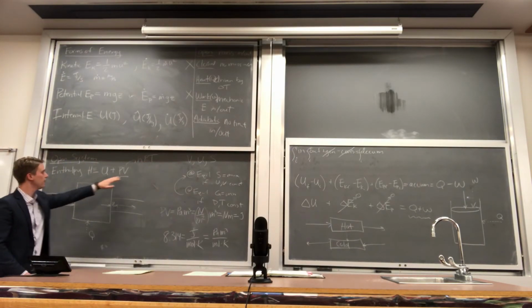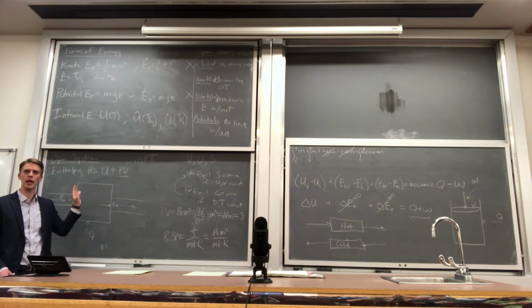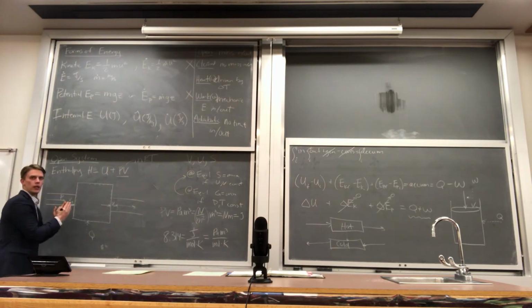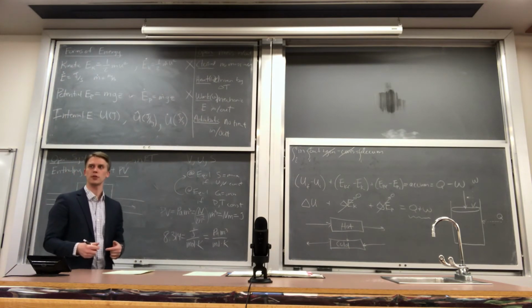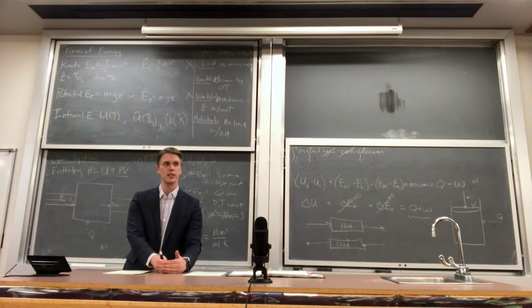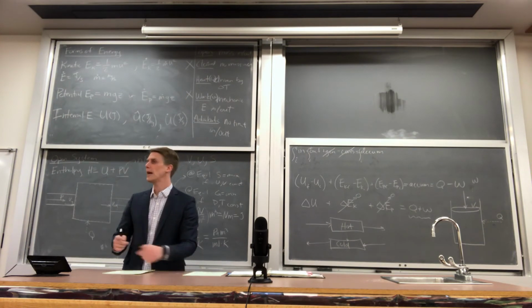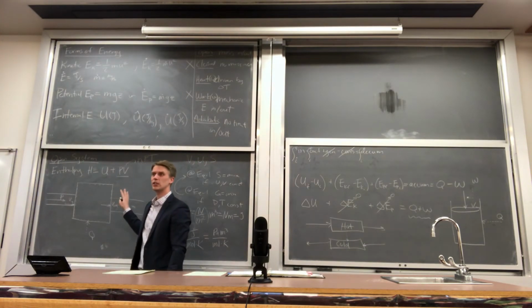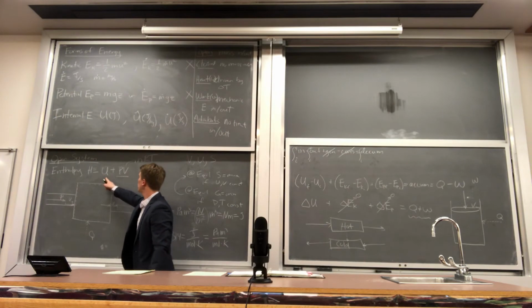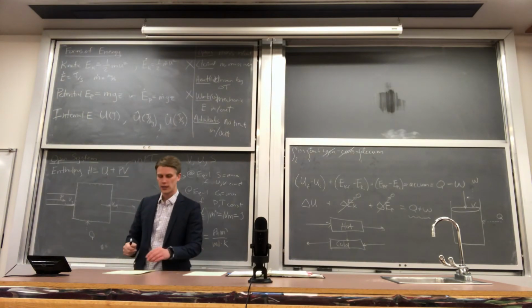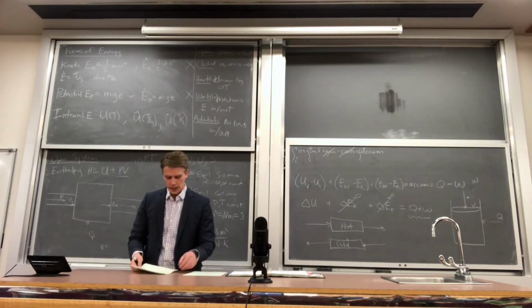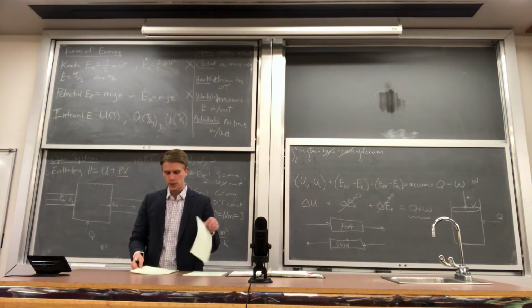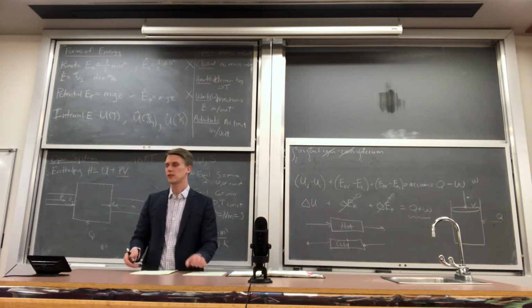For a real fluid, this is not the case, right? So for a real fluid, the enthalpy is different as a function of pressure and temperature. And so if you look at your steam tables, you'll notice that the enthalpy indeed does change when you change the pressure. But for an ideal gas, which is going to be the lion's share of our calculations, the enthalpy and internal energy are only functions of temperature. Now, the main reason why that's the case is sort of committed to more of an advanced thermodynamics class.